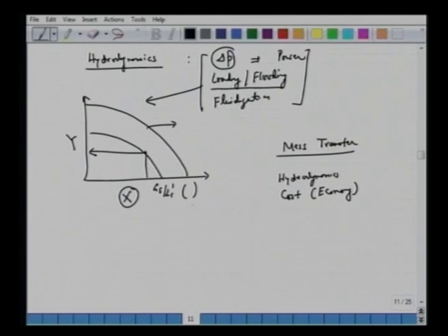because in case of, say, absorption, if you want to increase your liquid flow rates, then the cost of the solvent itself will be larger, or may prevent you from going for the larger flow rate of the liquid. Or one has to think of this: after this absorption you have the spent liquor, so one has to regenerate. So the cost also plays a major role in overall design, which I am sure you will have at some level next year onward.